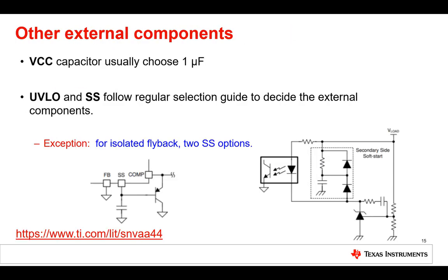Other important components for a flyback design are the supply of the controller IC and the components for the startup of the flyback converter. For a controller IC, it is essential that its own supply is as stable as possible. Therefore, a lot of ICs have VCC or VDD pins, which need a ceramic capacitor connected to create a stable IC supply. LM5155 needs a 1 microfarad capacitor.